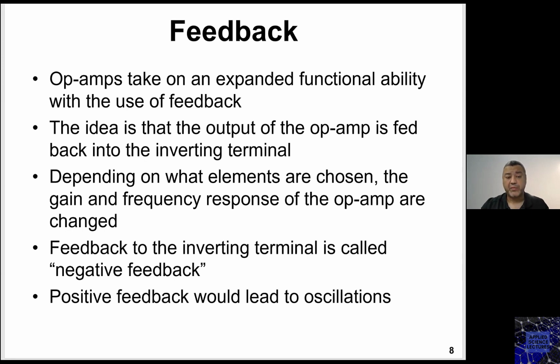The negative feedback is basically having the output reconnected into the inverting input of the operational amplifier, right? So this is how we do it. This is the negative feedback, by having the output connected to the inverting input of the operational amplifier.